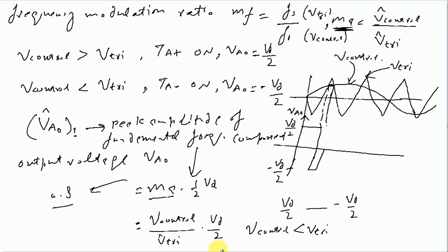So this relationship or equation shows us what we had discussed in the beginning about pulse width modulation, and also in one of the last lectures in which we had these three categories of voltage source inverters: that we can control the magnitude as well as the frequency of the output signal. Here we can see that this is the magnitude of the output and the peak amplitude of the fundamental frequency component, so by controlling the ratio of these two, we in turn determine the value of the output voltage.